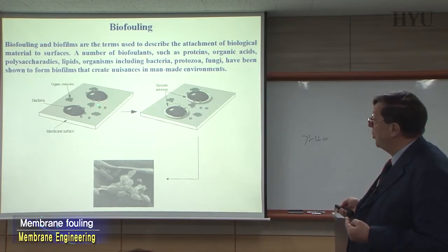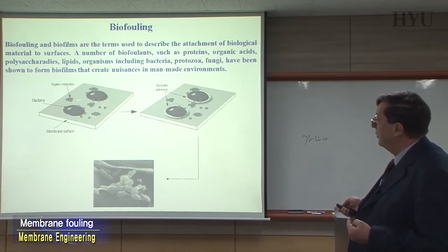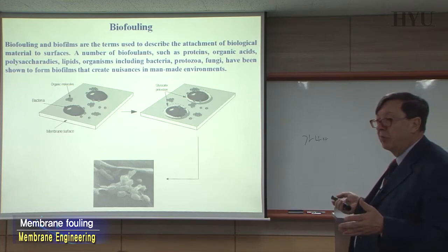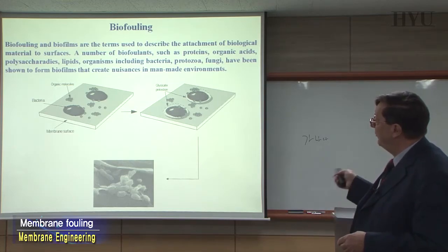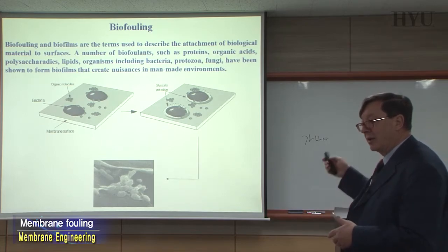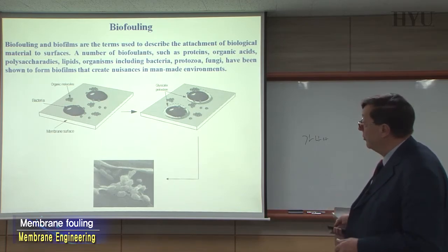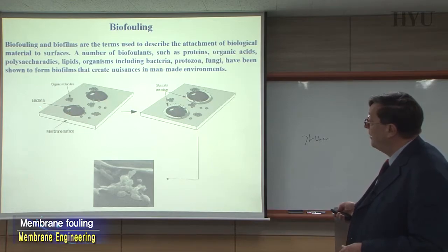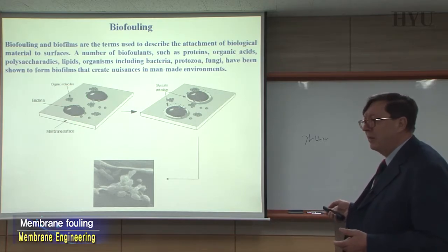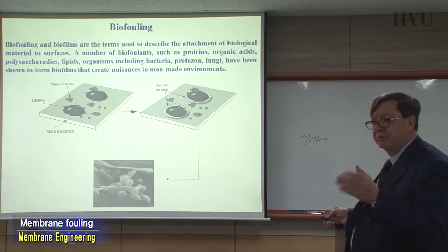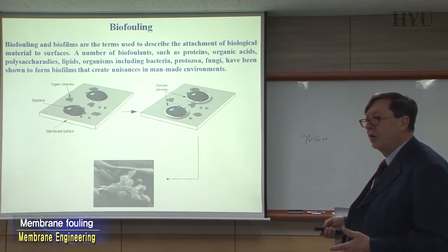When you have macroporous membranes, on the membrane surface you have some pores, and these small particles are going through with no problem. Eventually there is some fouling, but you increase the axial flow rate, you do backflushing, and everything's okay. When you have one or two big particles that are just absorbed on the membrane surface, you don't realize there's a problem. Only one or two big particles, osmotic effect zero. Too big, so very, very low osmotic phenomena.